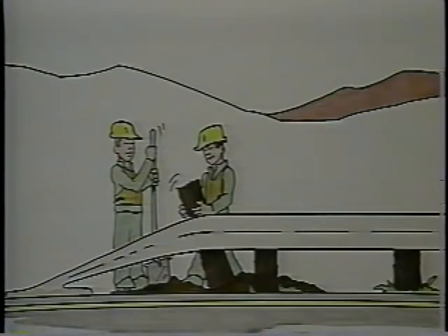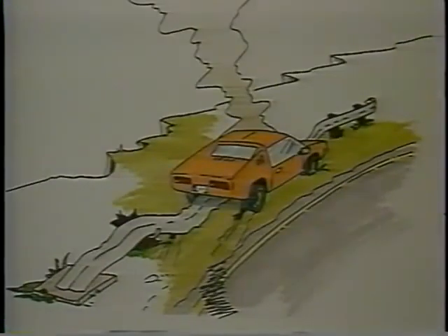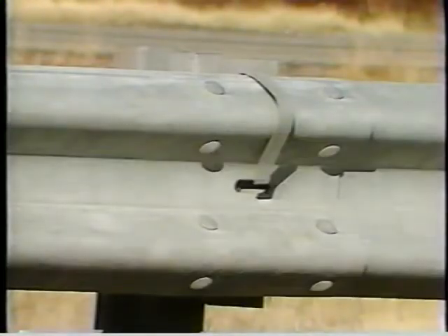Basically, what has been done to correct the problem involves removal of a post and rigging the railing so that it can fall down when impacted. This is called CRT, or Controlled Release Terminal. One variation is the clip and short section of W-beam. Other variations perform in the same manner. Fundamental to the system's working as designed is the requirement that the rail release from the supporting posts as soon as the end treatment is loaded with a downward force.